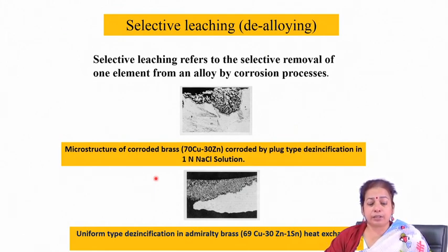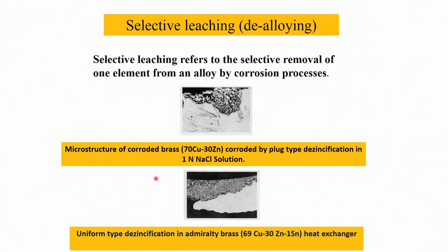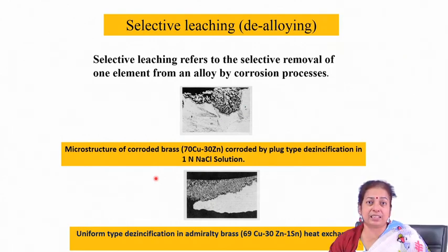So, we discussed the different ways to deal with these problems, and one of the important ways by which this problem can be solved is the solutionizing operation. If you talk about a surface treatment process which might be applied for mitigation of intergranular corrosion, that may be surface melting, because otherwise it is very difficult to mitigate this kind of problem. It is done by typical bulk heat treatment, or by addition of microalloying element in the microstructure during alloy development.